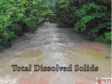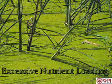With total suspended solids, suspended matter blocks the transmission of light, diminishing photosynthetic activity. The settled matter can cover the floor, damaging invertebrate populations and blocking spawning beds. Excessive nitrates and phosphates can result in overgrowth of aquatic plants, especially algae. This overgrowth means more organic waste in the water, resulting in a higher BOD. Also, algae blocks the transmission of light.